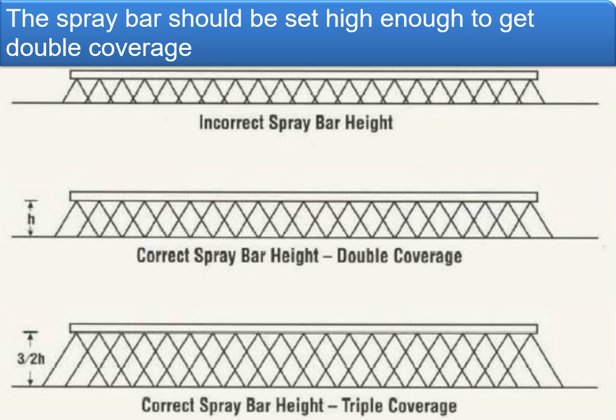So this is having the minimum coverage as far as the nozzle is concerned. What is required is that the height should be adjusted in such a way that the area covered by the first nozzle should have at least half of the area covered by the second nozzle overlapped, so that the quantity being sprayed on this surface area will be double the coverage.